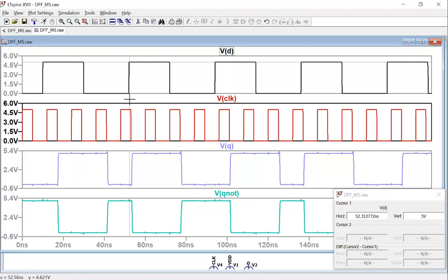So that's why, here is the falling edge of the clock, see? The falling edge of the clock triggers the change, okay? It's going to send a 1 to Q. So where is that one from?